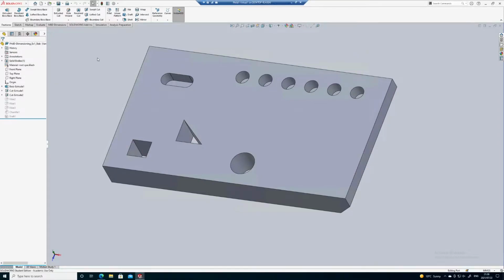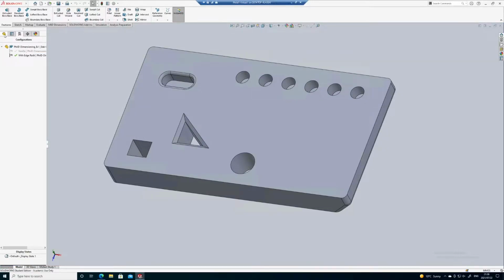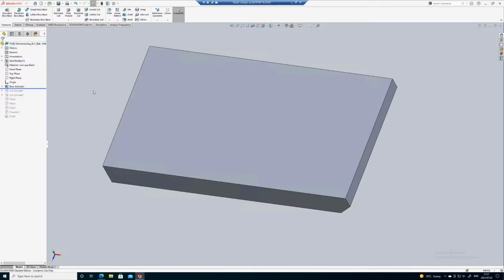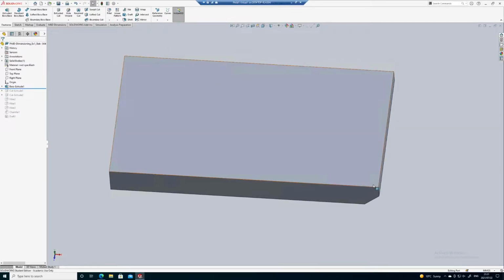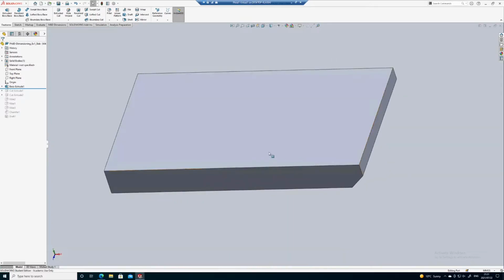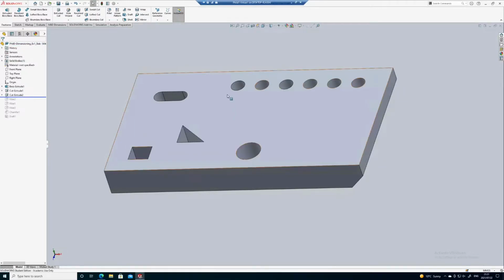I think the rest was that following a procedural approach in all that you do in CAD is absolutely vital. So start off with a very simple shape. So maybe let's just go like this. Start off with a simple shape. Don't put any radii in. Don't put any edge radii or corner radii. Add those in later. Then of course you can cut. So do the basic shapes first. Then you would put in any tapers if you needed to, which I don't have here. And then after that you can put in the fillets, chamfers, etc.